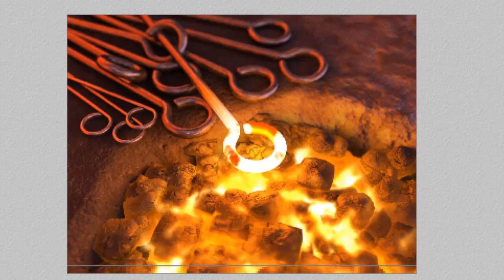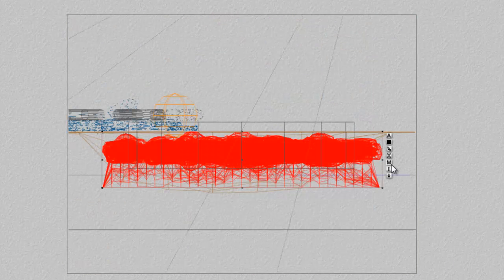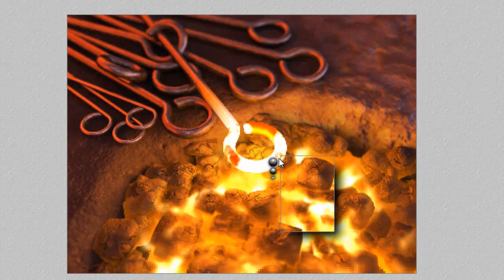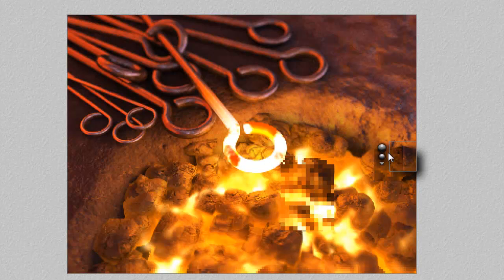Okay, I ran a little test there. That is faster, but it's now looking a bit too light because it was darker before. And one of the things about the true ambience is that it allows light to transfer around. Even ambient in the material becomes a light source. So what I can do is reduce the diffusion on this a bit so it doesn't turn so bright. Render a small area. See if that restores the balance a bit. I want it to be light to some extent, but still want contrast in that image. So right, we'll give that a render now.